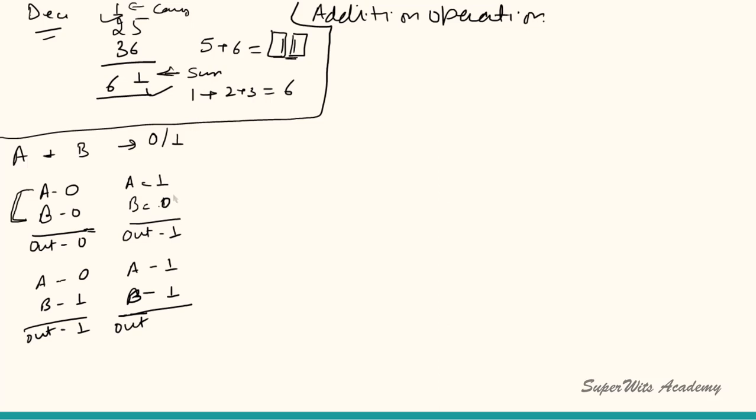If you remember the addition operation in binary, 1 plus 1 is 1 0, right? So 0 will be the sum here, and 1 will be given as a carry because there is no bit position available, since the data is a 1-bit data. So C is kept as a carry, but it will not be represented as part of the particular output. Otherwise this becomes 2-bit for me. Okay, so the sum is kept separate and the carry is kept separate.